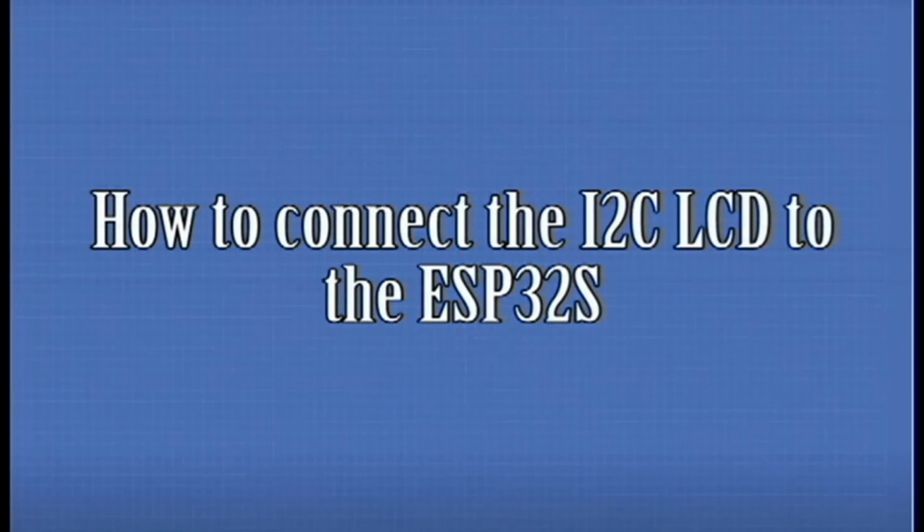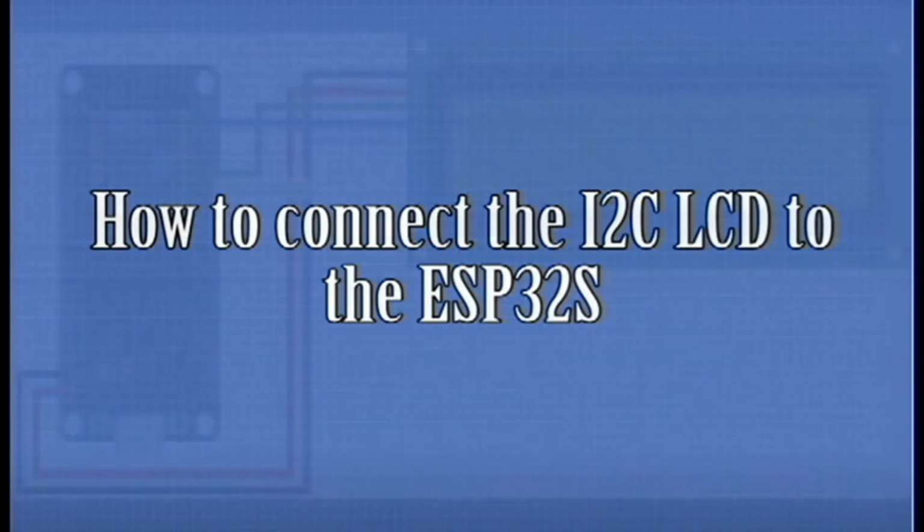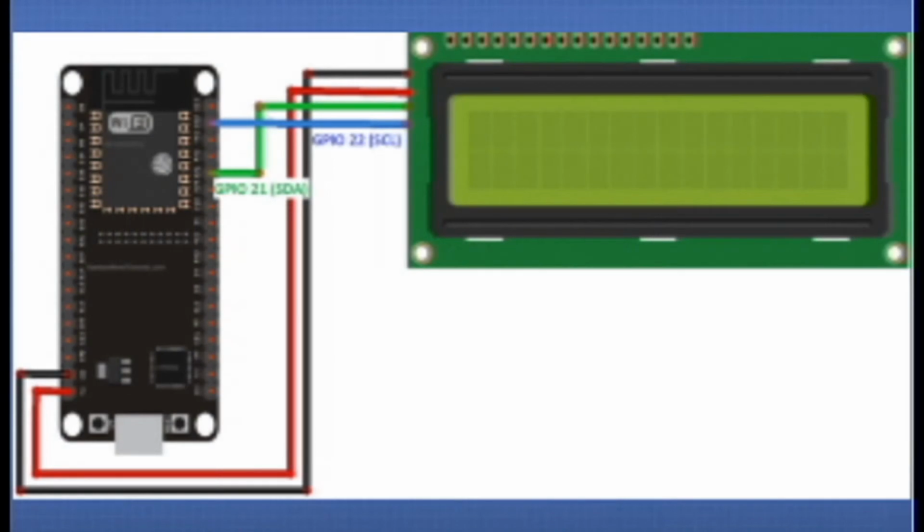How to connect the I2C LCD to ESP32S. This wiring diagram shows you how to connect the I2C LCD to the ESP32S. Wiring an I2C LCD is a lot easier than connecting a standard LCD. You only need to connect 4 pins instead of 12. The ground to the ground, the VCC to 5 volts, the SCL to pin 22, and SDA to pin 21.